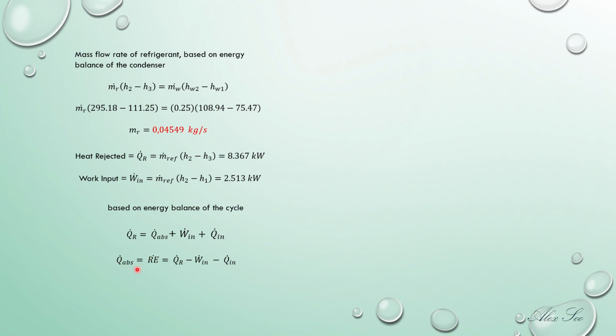By putting in all these values, you will find the cooling load, that is 5.404 kilowatt. So the COP R, the coefficient of performance for the refrigerator, is 2.15.